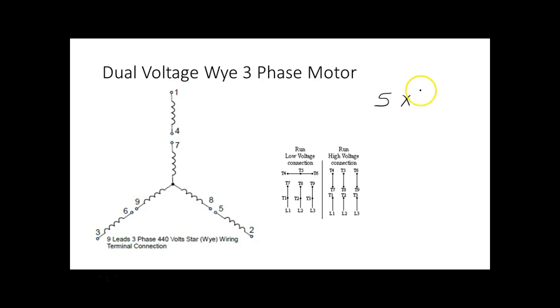How'd you come up with that? Yeah, there you go. So what did we come up with? 3730. So if I wired that thing for 240, this would be I equals P over V. How much current would it take?